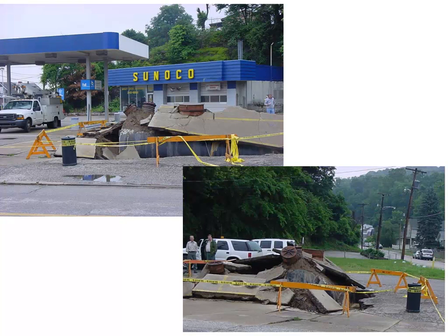Let me just get the lights again. Here are a couple of photos that show it from other angles. Certainly gasoline can cause a tank to expand, because it's highly volatile. But in this case, what happened was that the gas levels got very low, so that the weight of the tank plus the fluid inside the tank was less than the buoyant force of the water table, causing the tank to float. If that doesn't make sense at first, don't worry, it will.